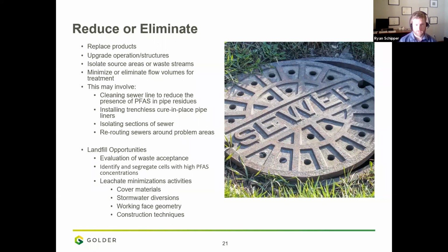the total amount of leachate, making sure that your stormwater diversions are designed and implemented correctly, as well as looking at working phase geometry and different construction techniques that can be used to reduce the overall volumes of leachate, and therefore the volume that you need to manage potentially for PFAS.